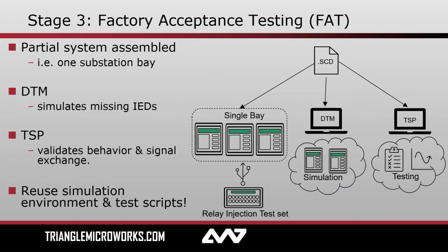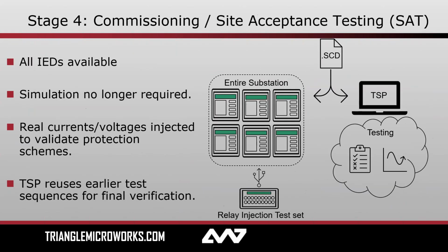Of course, Test Suite Pro can still be used again to run those tests, to control my injection tests, and then to validate the communications that are coming out of both my real physical IEDs that I have present, as well as those that are simulated in DTM. And in many cases, I can reuse test scripts or test sequences that I wrote in phase 1. We will also be seeing this in action in the second part of this webinar, which will happen after our engineering process webinar.